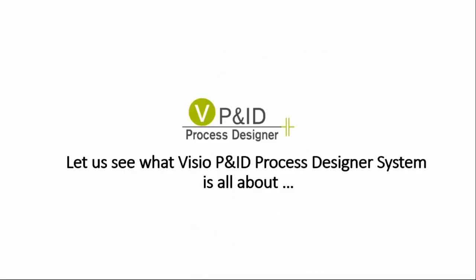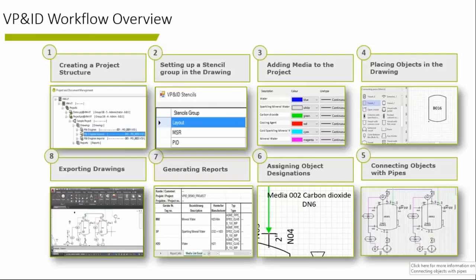Now let us see what Visio P&ID Process Designer System is all about. Using Visio P&ID you can create P&ID drawings in 8 steps. So this is the workflow overview. You can start creating your project structures and database first. Then you can set up your stencils group in your drawing where you will have your intelligent symbols. Then you can add your media, that is services, to your projects. Then you can start placing your objects from stencils to your drawing area.